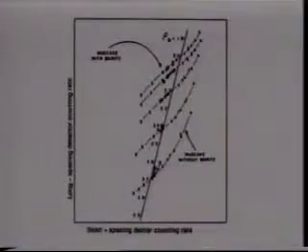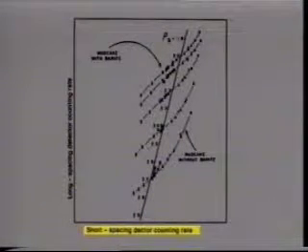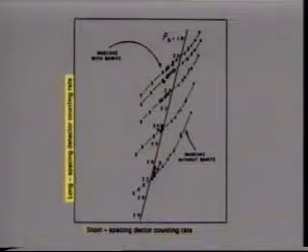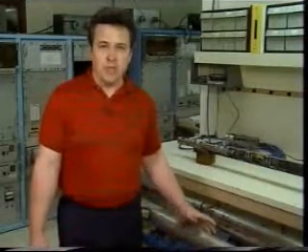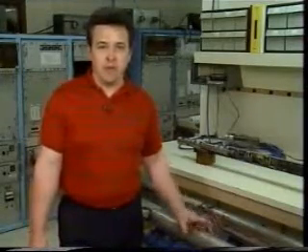Corrections must be made for the effects of mudcake and bore wall rugosity on tool position and gamma ray absorption. This is done by evaluating the differences in response between the close-space detector, which senses primarily the bulk densities of the mudcake and bore wall irregularities, and the long-space detector, which senses both of these, plus the bulk density of the flushed formation.